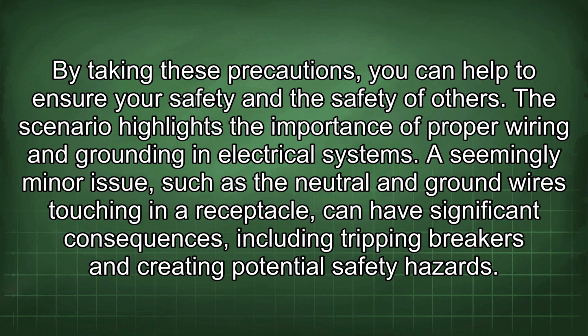The scenario highlights the importance of proper wiring and grounding in electrical systems. A seemingly minor issue, such as the neutral and ground wires touching in a receptacle, can have significant consequences, including tripping breakers and creating potential safety hazards.